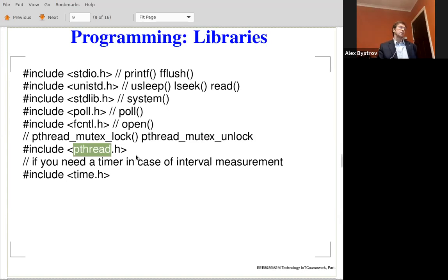It was the lecture about the algorithms, for example, the encoder, and the encoder is within a measured interval of time. We count interrupts. So one thread forms this measured interval of time. Right at the beginning of this interval, it resets the count, and then the counter counts 1, 2, 3, 4, 5 as the interrupts hit us, right? And then at the end of this measured time interval, we read this count and produce the output.